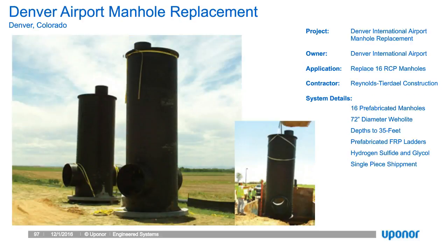Example of a manhole project: we produced 16 manholes for the Denver airport. These were replacement manholes replacing concrete structures that had deteriorated due to H2S and glycol. And these particular manholes were fabricated to accommodate aircraft loading as well.